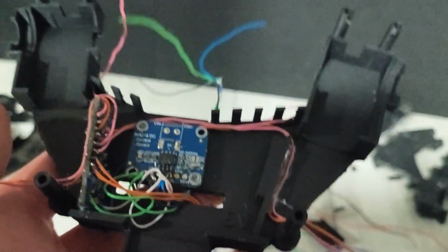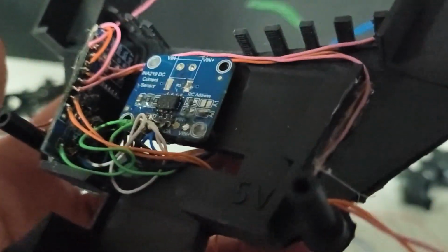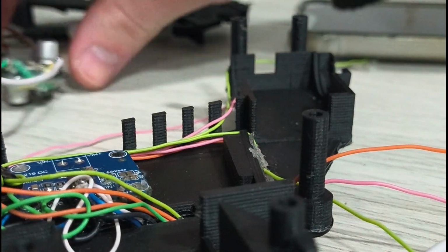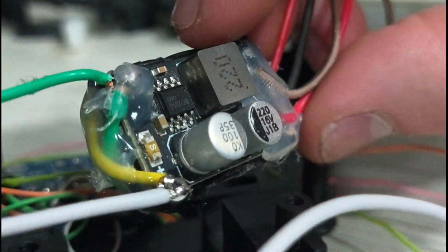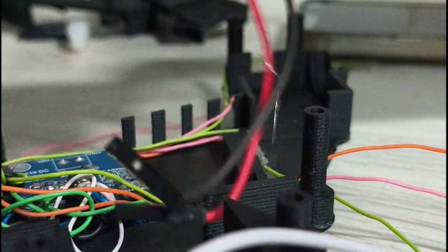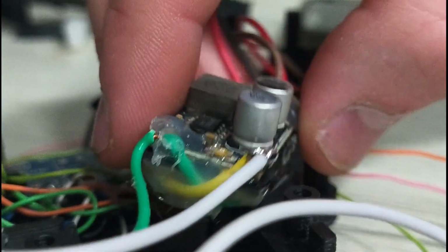So you might want to wire it together a little bit better than this, but now it's time to turn our attention to the 5-volt boards. You'll have 2 of those 5-volt boards trimmed down and turned into a sandwich with an insulative layer like this. So you get one 7.4 volt input for 2 5-volt rails.